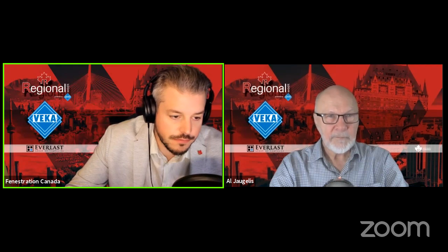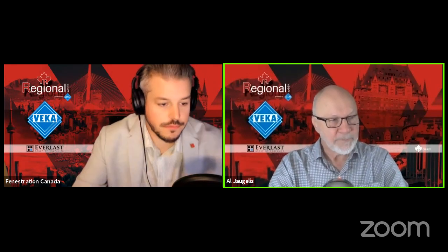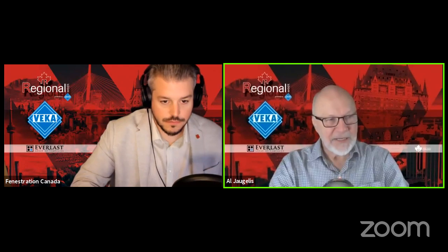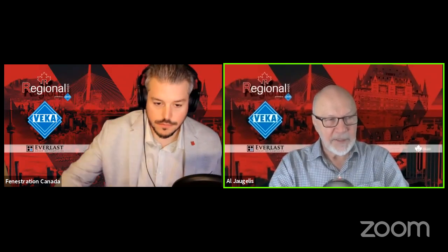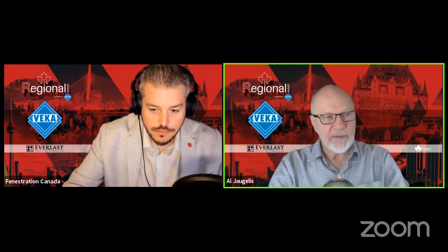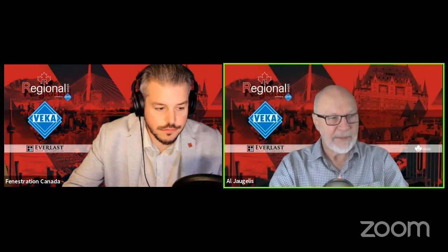Are there specific criteria to define site-built doors? To be honest, I'm not clear what they mean by site-built doors in the code. That terminology exists in the NAFS standard. The NAFS standard exempted site-built door systems from testing. I suspect that the people that were involved in Part 5 of the code just pulled that language out of the NAFS standard.